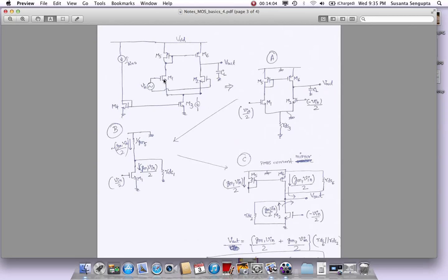So it has a differential input, it has a single output, and let's see how this thing provides gain and where are the different poles and zeros in the circuitry. Okay, so this is also an amplifier, and again the output has some load capacitance modeling the load that it could be driving. Okay, so the first simplification is same as what we did before. We have a differential source, so we'll break it into two sources, one side being Vin by 2, the other being minus Vin by 2.